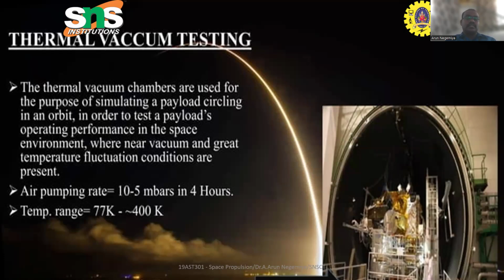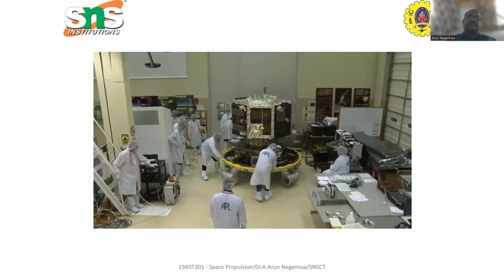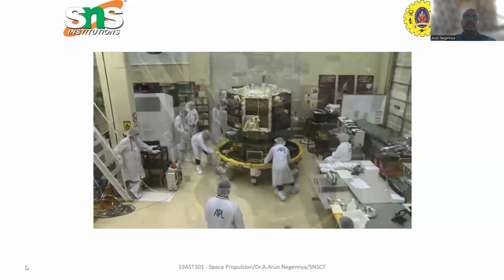The temperature range is 77 Kelvin to 400 Kelvin, the holding time is 4 hours, and the vacuum pressure is 5 to 10 millibars. How much temperature the payload can withstand should be evaluated in this testing. These are the thermal testing methods.